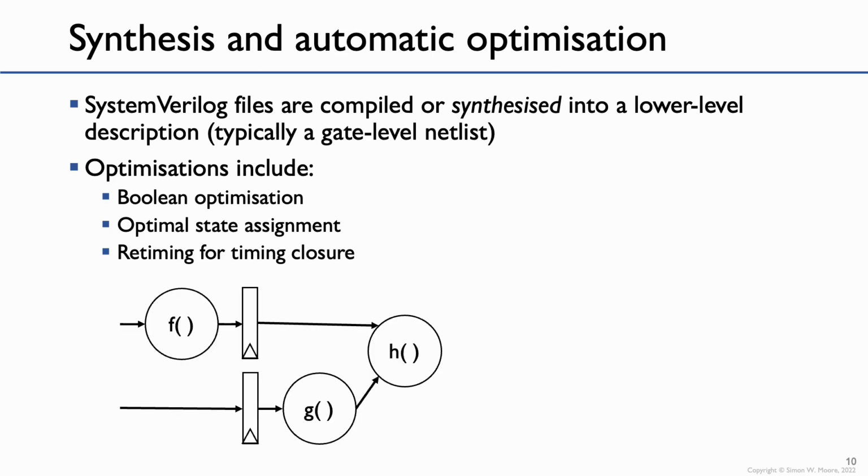So if we've got an example circuit as follows, here we've got some function F where the output goes to a flip-flop, and then on the other side of the flip-flops we've got functions G and H. Well, imagine G and H just taking a bit too long, so that the output of H, that will presumably go to another flip-flop, can't meet the timing requirement.